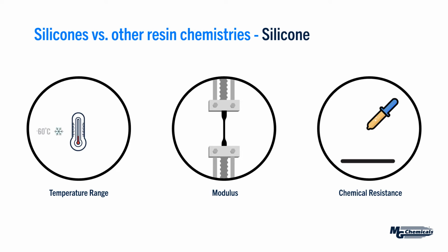And then finally, when we look at silicone, well, that tends to be a case where the operating temperature is sort of enhanced over the other chemistry options. Typically, it's about minus 60 to 200. But again, there's some materials that range from about minus 115 Celsius to up over 300. So that tends to be where it is most likely used when you have that higher temperature or just a wide operating temperature demand. Silicone tends to be a preferred material here.